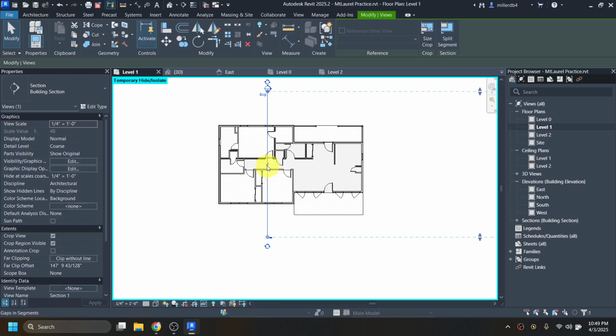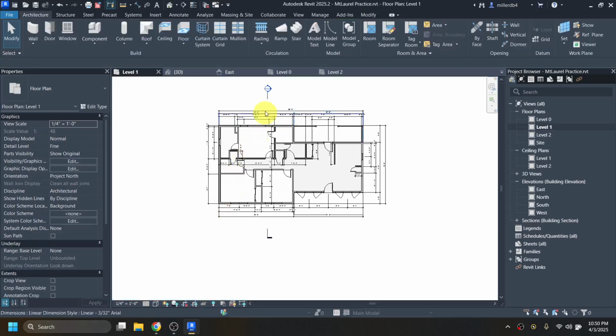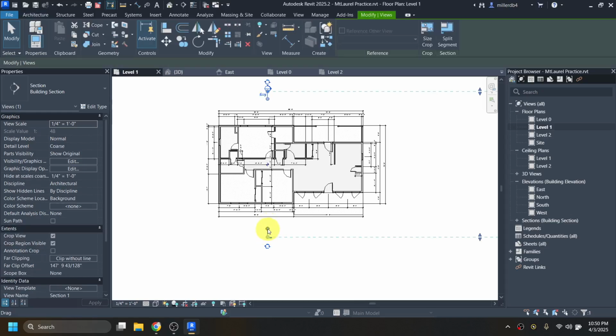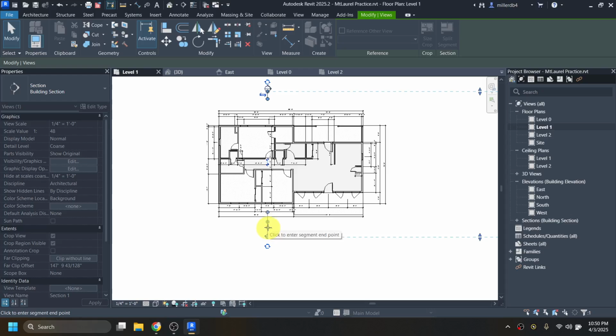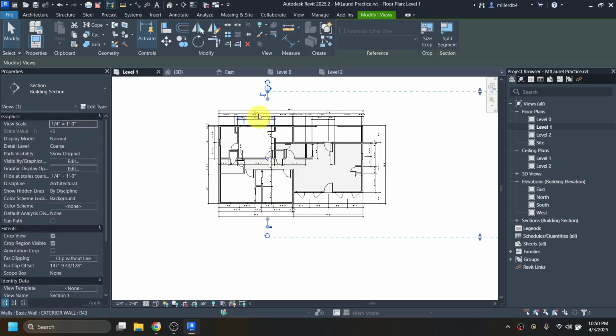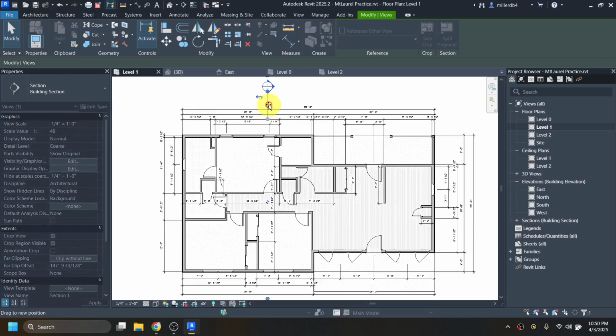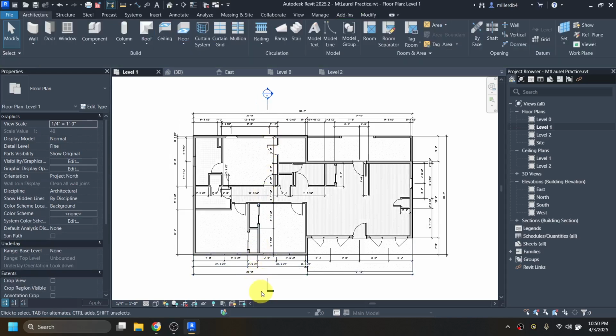We also would like to split our section into just a head and just a tail, and I'm going to turn off my temporary isolate for my dimensions, so I'm going to reset so they come back, because what I want is to make sure that this head and tail are not interfering with any of these dimensions that I have. So I don't want them overlapping any of those dimension lines, so that it's not this extra line in there busying things up unnecessarily.